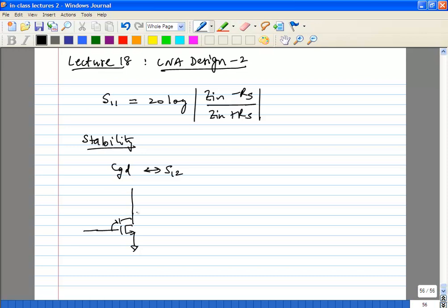So one of the things you have learned is we use resonant circuits all over the place, right? So let's say we can tune out this CGD with a parallel inductor, but of course you can't connect it directly. You need a large capacitor. Let's call it CB. Okay, you can do something like this. You can use your inductor to tune out the gate drain capacitance. So that is one way. It's kind of a brute force way, but you can do it.